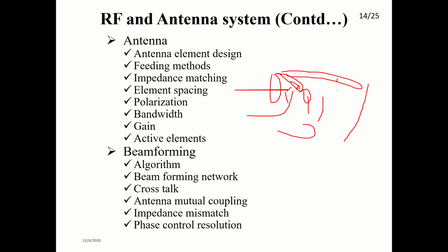And what is the cross polarization requirement? What is the side lobe level you are looking for? And what should the antenna size be? Because here you are not going to design only the antenna alone, you are going to integrate that with the radio itself. So what sort of requirements will you have, because the size is limited and everything is limited.